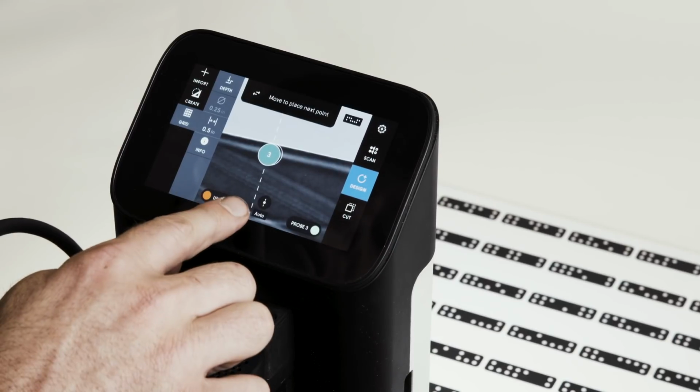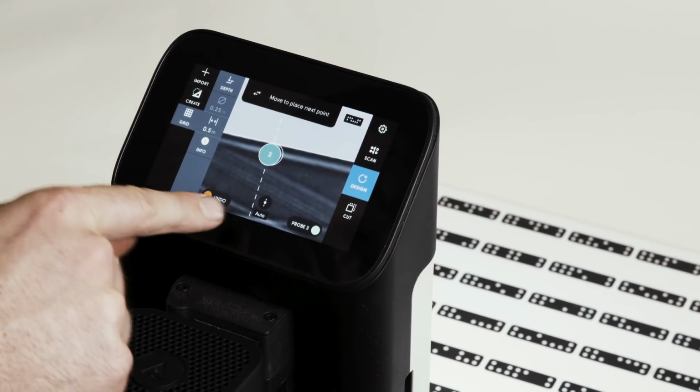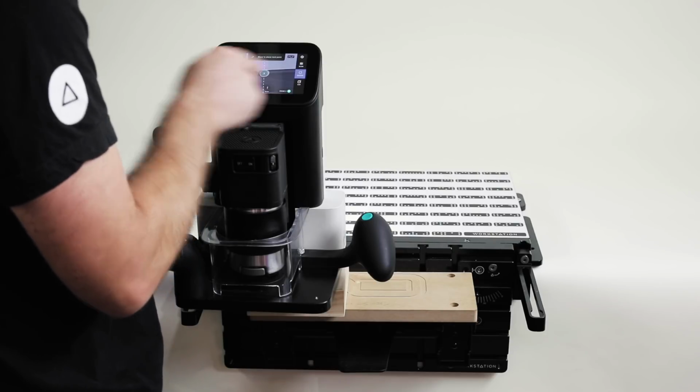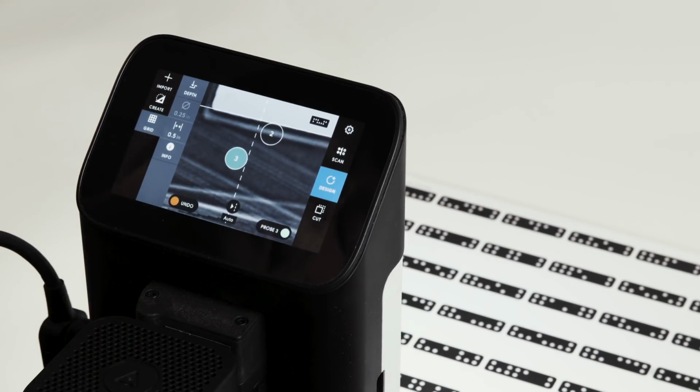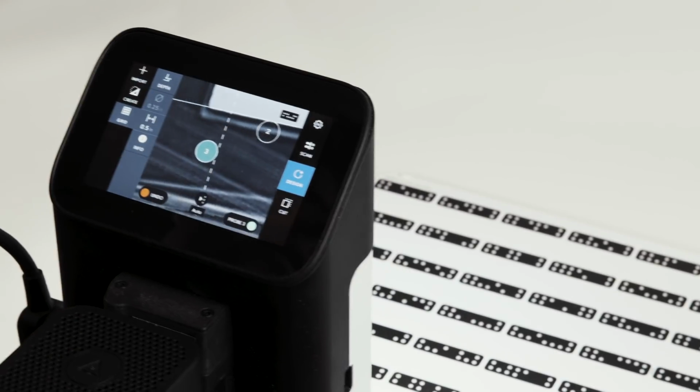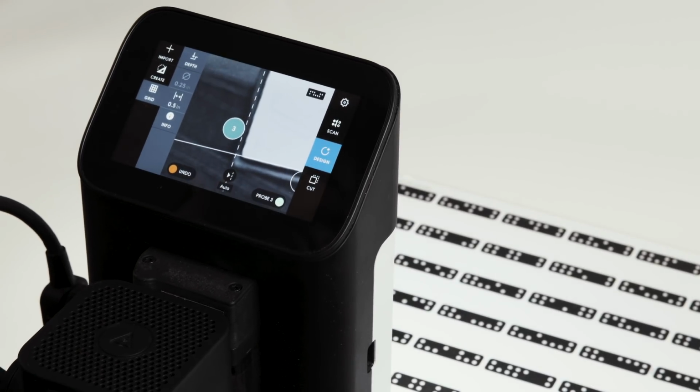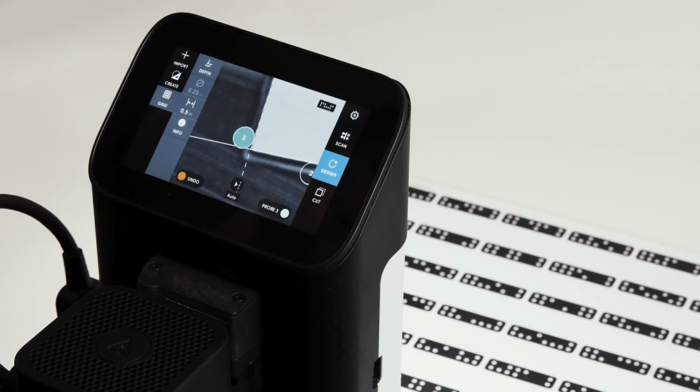And you'll notice this is auto. It's currently using the center. We'll get to that later. But as I round that second point, you'll notice it swaps automatically to the right-hand side of my probe. That's because it's anticipating we're going to come through here and do a standard probe against this edge.